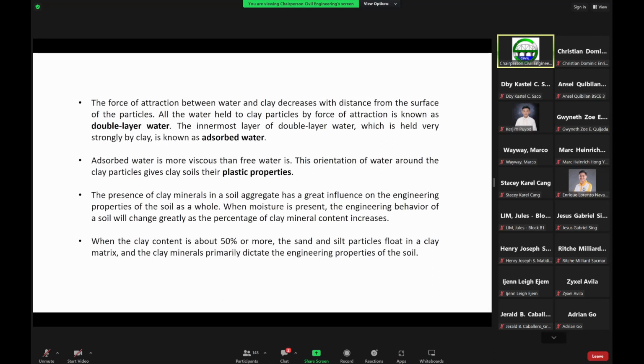That's why there's what we call a low plastic clay and a high plasticity clay. Again, in practice, we really don't like these plastic clays because they are a bit problematic. We would prefer a low plastic clay, for example. Later on, we will be discussing that. So this just explains why we have the plastic properties.